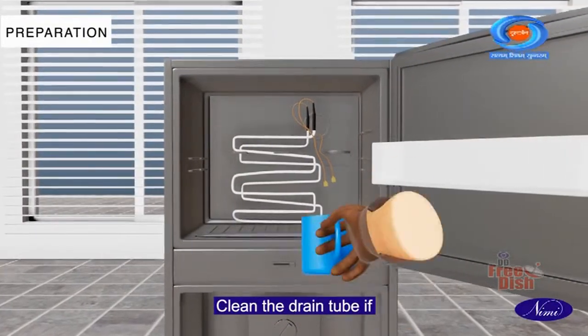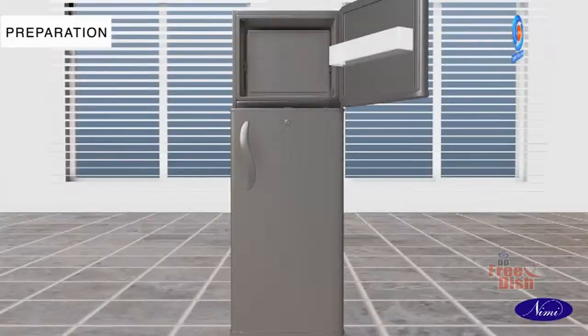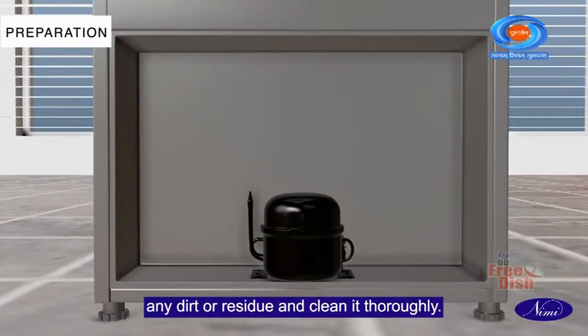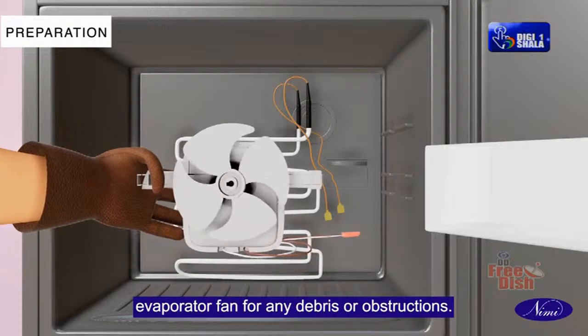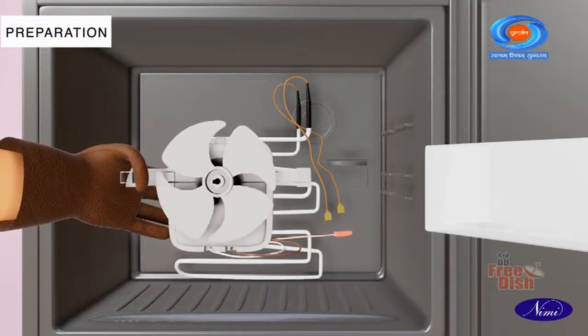Clean the drain tube if necessary to prevent water collection. Check the drain pan beneath the evaporator cabin for any dirt or residue and clean it thoroughly. Remove the evaporator fan grill and examine the evaporator fan for any debris or obstructions.